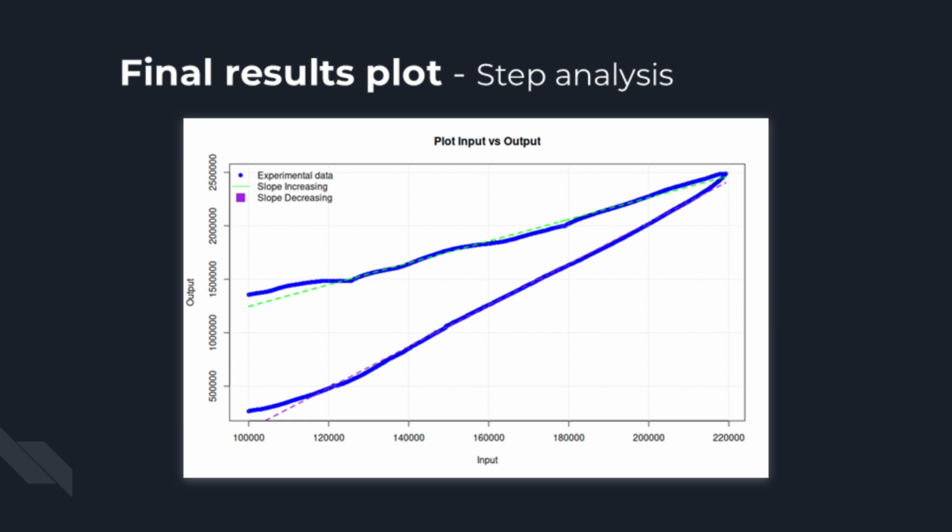This graph shows the results from a step test. Similar to the previous case, we can observe significant hysteresis due to the mechanism shifting inside the faulty V-groove. This makes it difficult to extract precise conclusions about the system's behavior. Additionally, we encountered issues with the laser losing focus during several tests, making most of the data difficult to interpret.